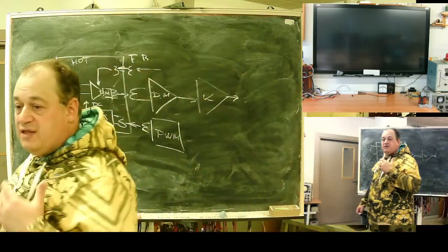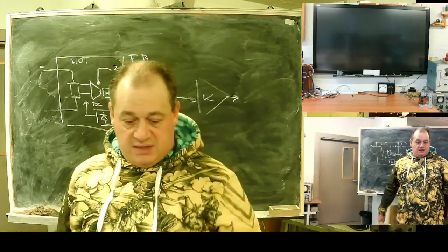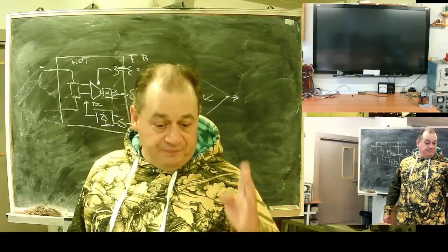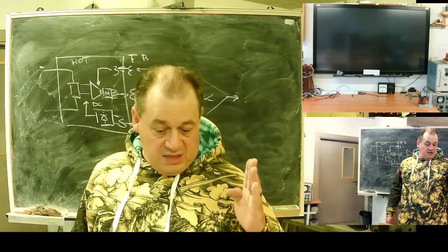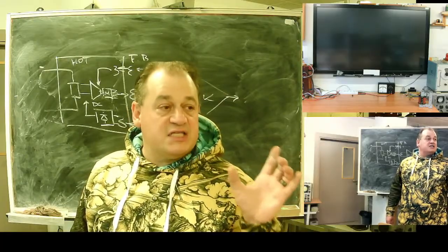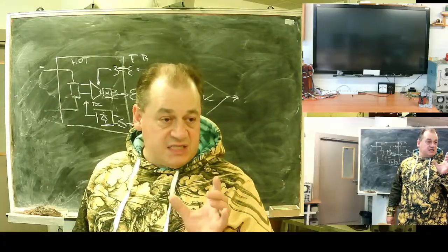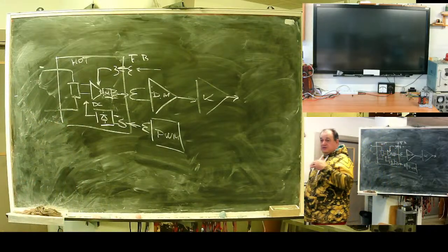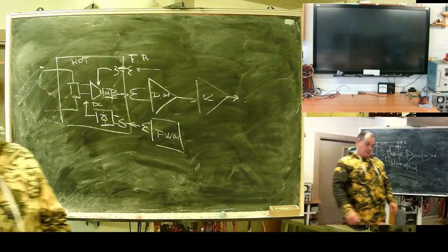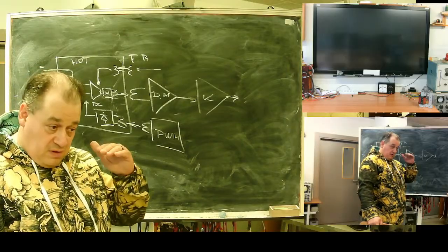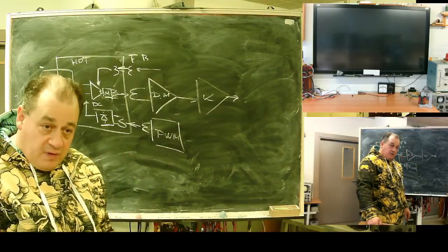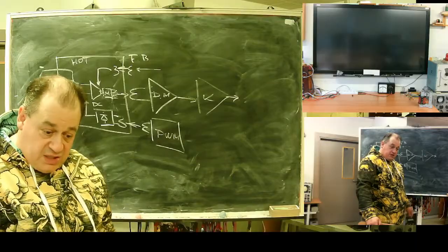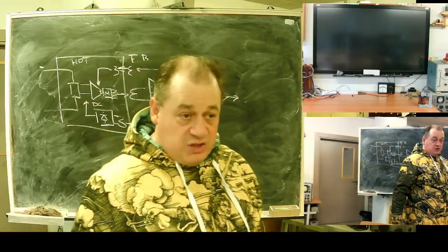The idea: how can we ensure this size of dynamic range with speed and range extension? Having somewhere in our analog part a switchable amplifier, then DSP multiplies as needed. For example, we have a 10-bit ADC plus 3 bits achievable with switchable range.